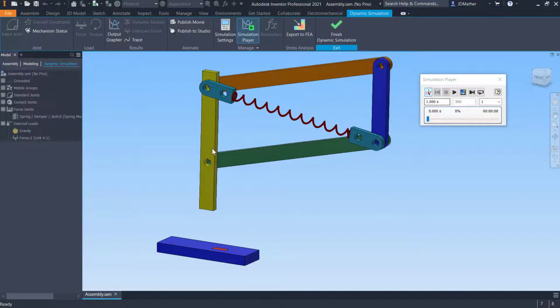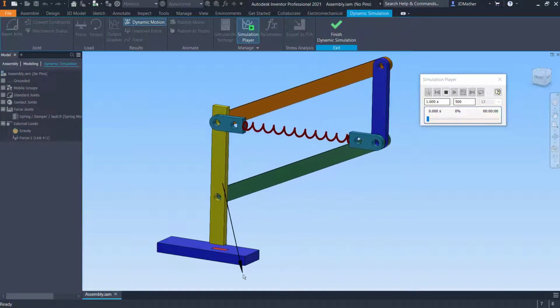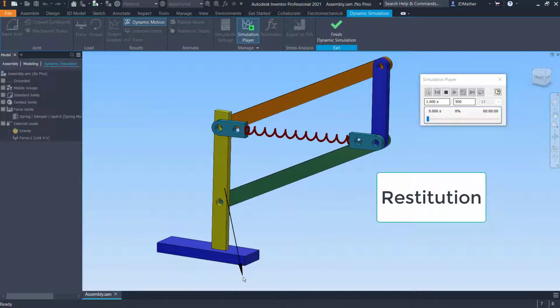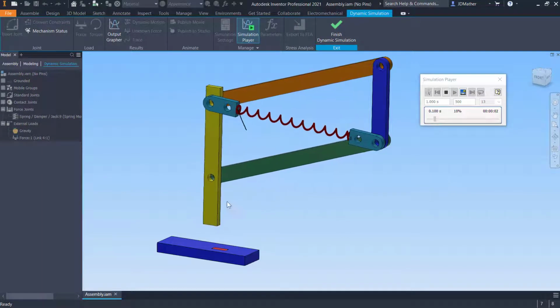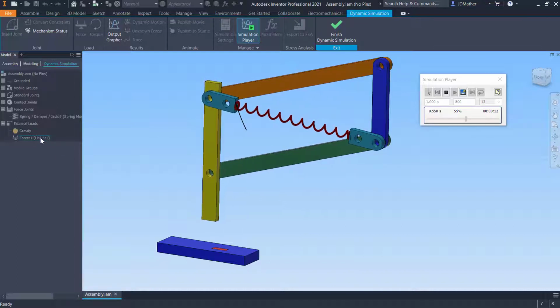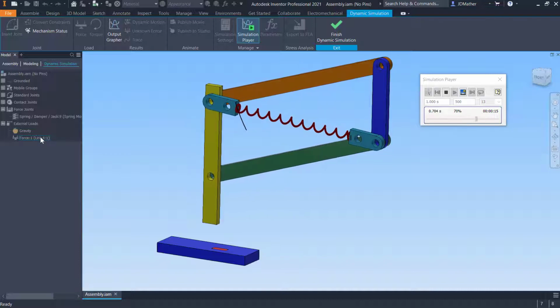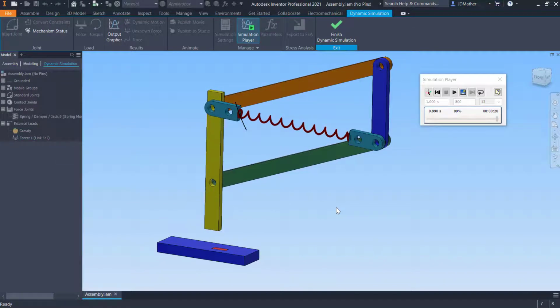If I drag this mechanism so that it's down against the table. Of course, we've seen how to set up that resistivity for the bouncing, and I will then play this again. We see that the downward force at the beginning was not enough to keep this down, and then the force increased. Remember, we graphed that from 0 to 10 newtons over 1 second of time. So a lot of variations that we can put in here for our 4-bar mechanism, and the mechanism could take a lot of different configurations depending on our application.